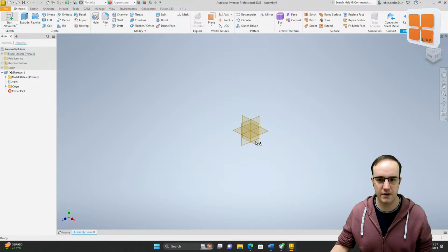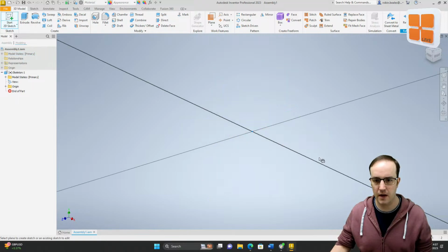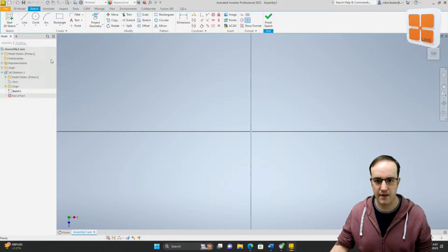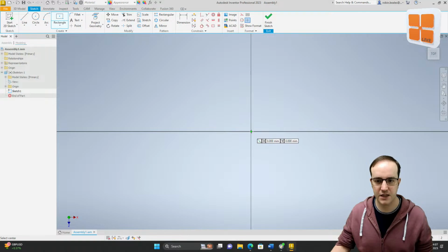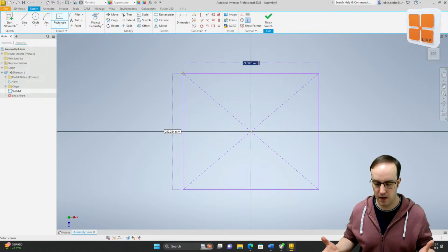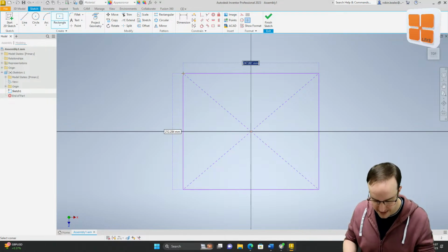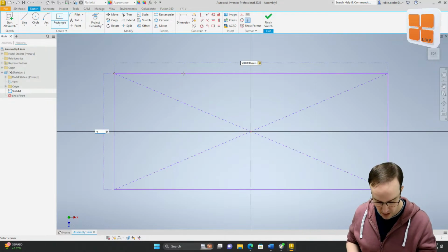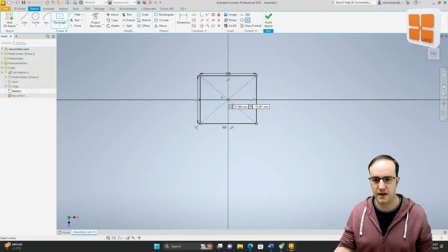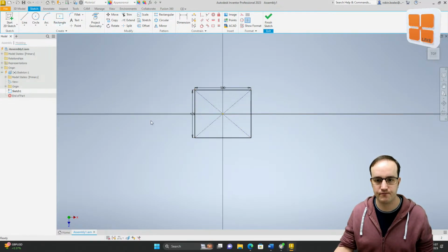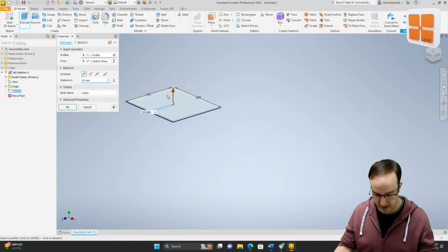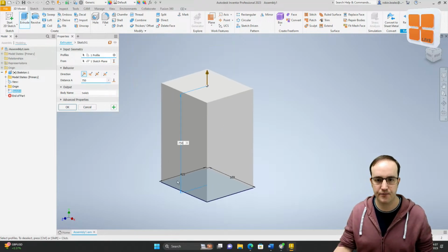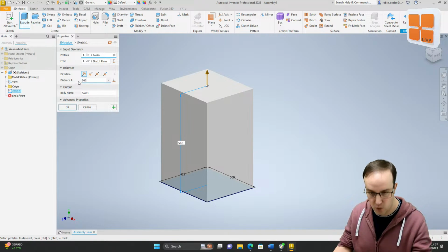So in here, I'm going to create a new sketch. I'm going to use the XZ plane here, just to create the top-down view of this particular piece of framework. Let's place a 2-point center rectangle, and let's say that I want my frame to be not overly massive. Maybe we'll go 500 by 425 with regards to size. Something like that is absolutely fine. Let's go ahead and finish the sketch and extrude, and I want this to be about 750 millimeters high. So I've got something that looks a little bit like that, maybe a little bit less. Maybe we'll go with 540.